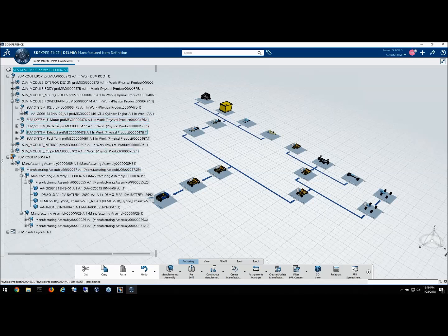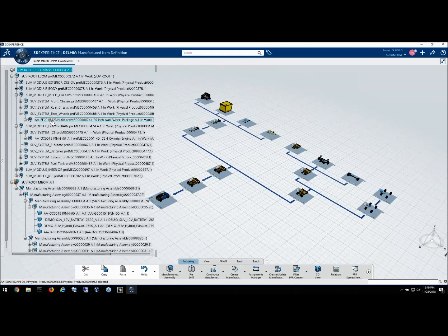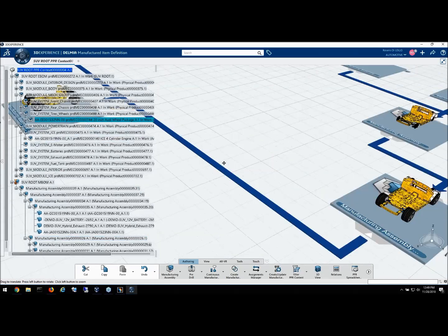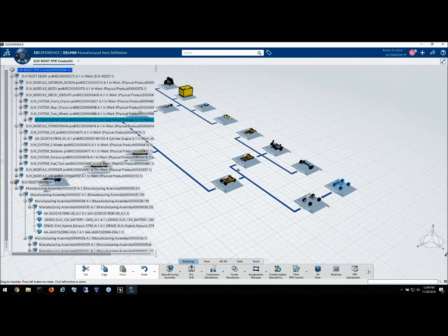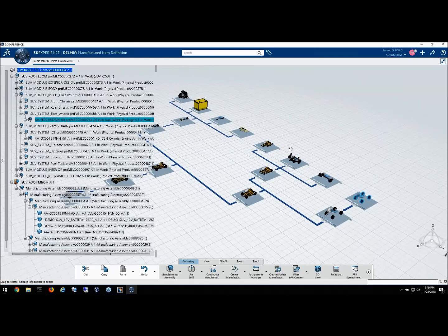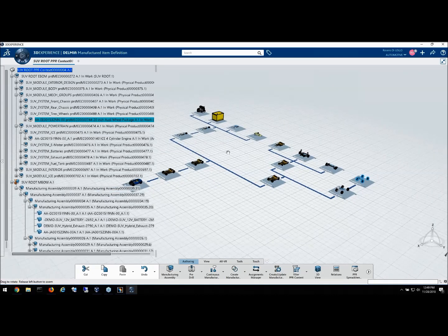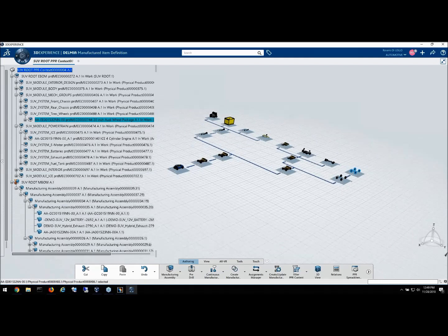You can see that if I go into the mechanical groups of the EBOM and open the wheels, I only have one choice of wheels, and this is reflected in the MBOM. So MBOM consumes EBOM, but it also consumes CATIA V5 data, CATIA 3DX data, and the centrally defined configuration of the corporate dictionary. So again, a very big argument with very little time.